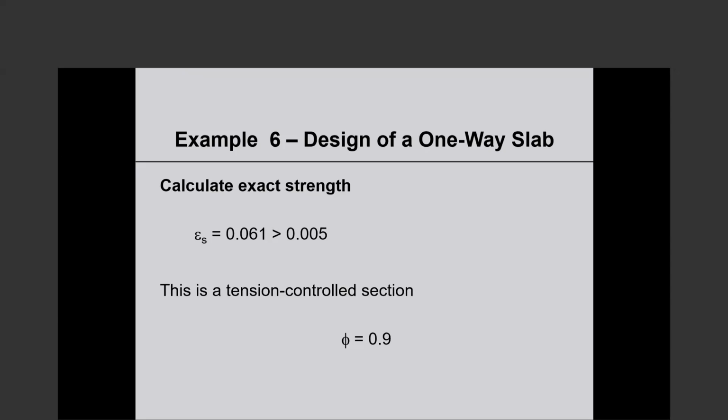that the concrete strength switches you from under reinforced to over reinforced. I think you're talking in old terms, 3/4 of rho balanced. Your under reinforced is up to 3/4 of rho balanced, and you went just a little bit beyond. I think that's what you are saying.